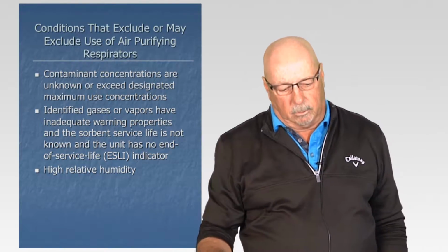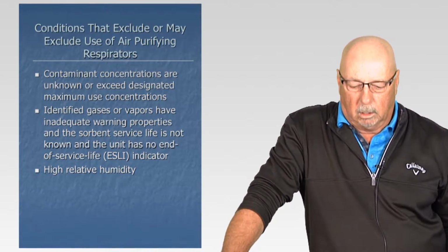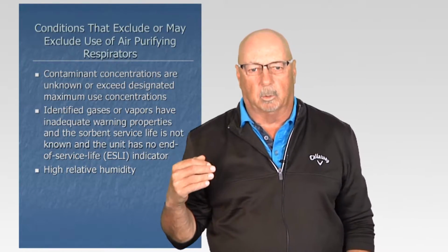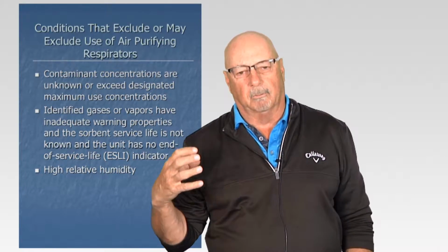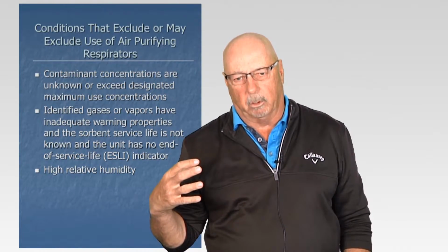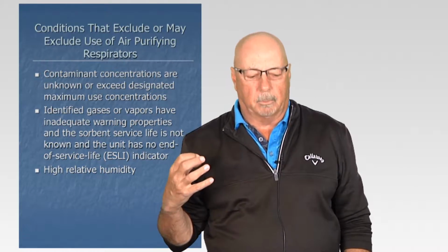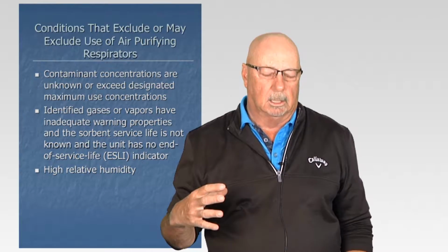Again, when we get into contaminant concentrations which are unknown or exceed the maximum use concentrations, now respirators, depending on whether it's a half mask or a full face mask or a powered air purifying respirator, will have a protection factor value assigned to it.